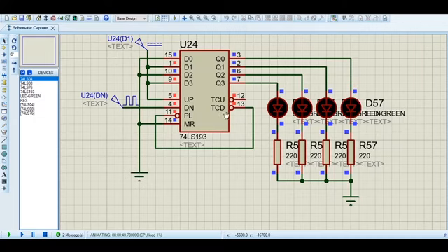This means that we can use this pin to trigger the load input after the last count of 0 in order to load these parallel load inputs to the counter and show them at the output. The count starts again at 10 and then repeats. So therefore, we shall only see the count of 10 down to 0 continuously, as you can see here on the outputs.